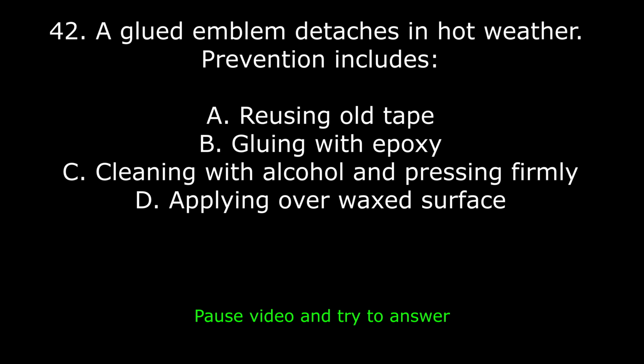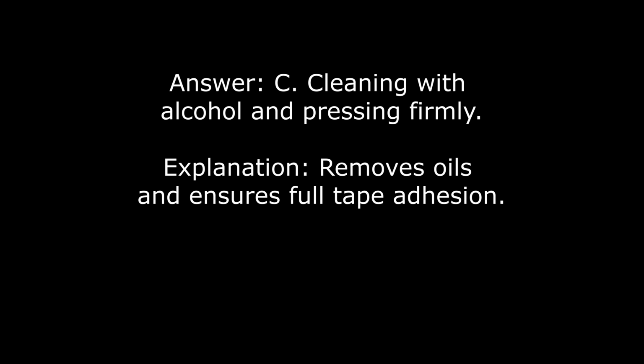42. A glued emblem detaches in hot weather. Prevention includes A. Reusing old tape. B. Gluing with epoxy. C. Cleaning with alcohol and pressing firmly. D. Applying over waxed surface. Answer: C. Cleaning with alcohol and pressing firmly. Explanation: removes oils and ensures full tape adhesion.